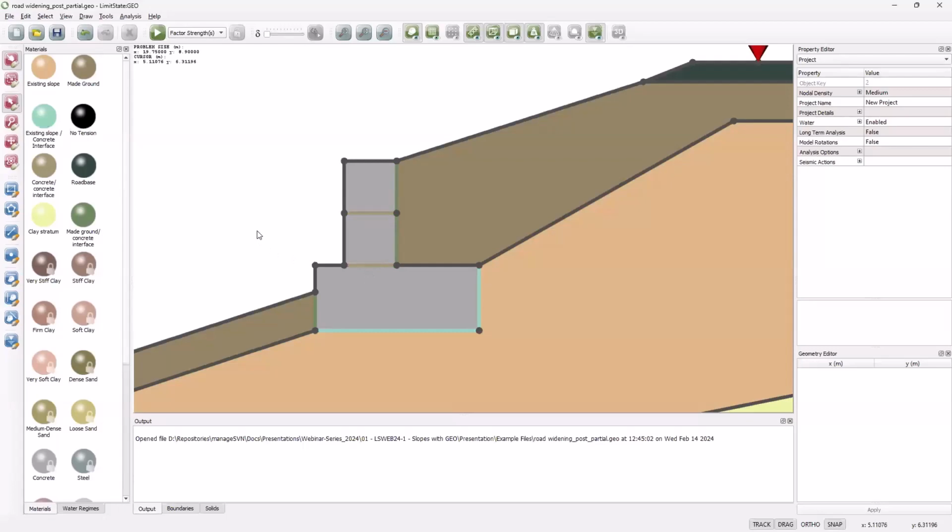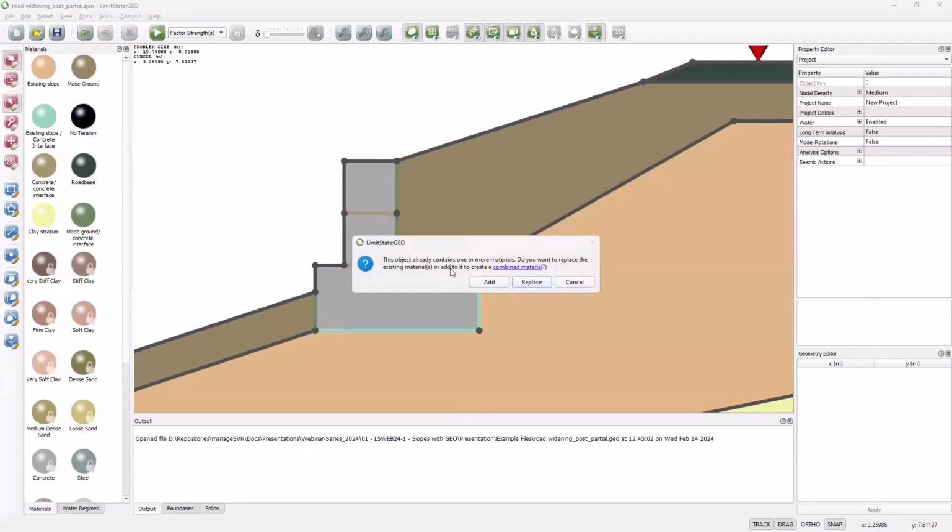But also, if I have concrete blocks sat on each other, they might be able to tilt, and so it's quite useful to put in what we call a no tension material, which effectively allows you to specify limiting compressive and tensile strengths. If we set the tensile limiting strength to 0, it means no tension can be sustained. And that basically allows rocking behavior. Probably won't happen in this case, but we put it in anyway.